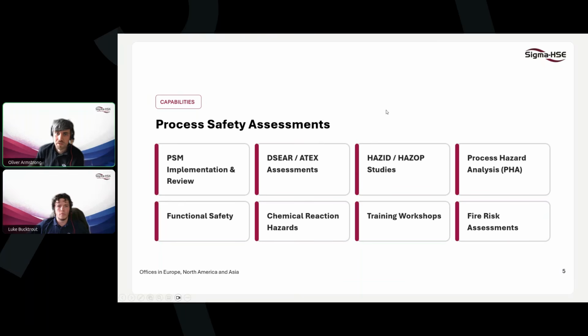Some of the assessments that our teams can assist with look to firstly identify potential hazards in systems and processes, such as HAZOP, PHAs, and so on, while others can look at mitigations or the integration of mitigations and controls and proactive methodologies. Each of these assessments should be chosen and applied based on the niche requirements of a certain process under assessment, or indeed the phase of construction or planning for a new facility.